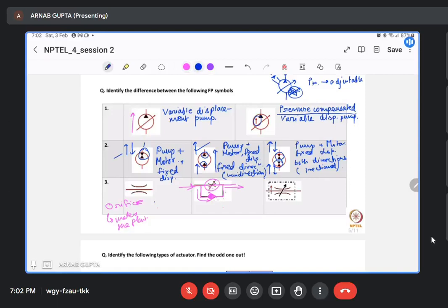Whereas if the fluid is coming from this direction, then this ball opens up and it allows the liquid to flow here. And since this is causing a resistance and this is the least resistance path, the backflow won't be metered. So this is only meter-in flow; the backflow is not metered.